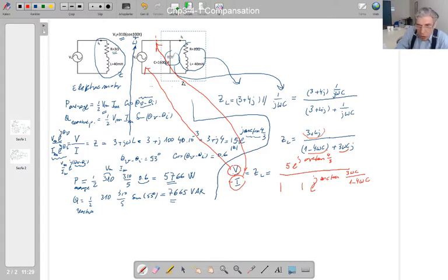So this is now theta v, that is theta e. What I am expecting is that theta v must be equal to theta e. That means that angle is 0, isn't it? The difference is 0. Sine 0 is 0. So my reactive power is going to be 0.